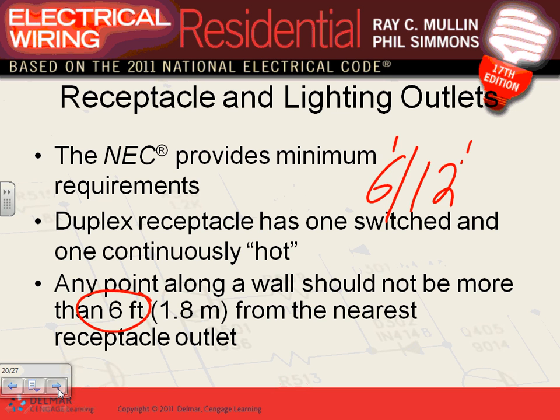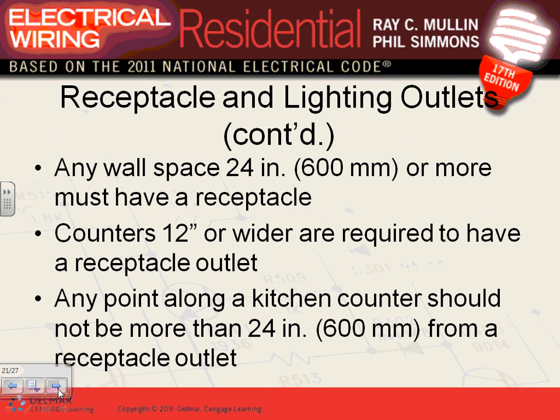All habitable areas, excluding unfinished basement, garage, outdoor, excluding bathrooms. These are non-habitable. Including all bedrooms, living rooms, kitchens, hallways. No, hallways are an exception, I'm sorry, because you don't put your bedroom in a hallway. Any question, guys, about excluding stairways? Everybody knows that rule, 6/12.